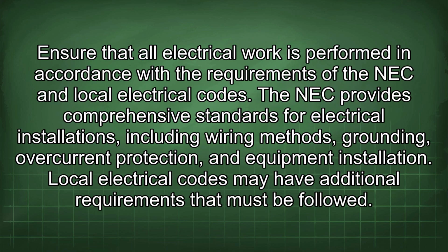Ensure that all electrical work is performed in accordance with the requirements of the NEC and local electrical codes. The NEC provides comprehensive standards for electrical installations, including wiring methods, grounding, overcurrent protection, and equipment installation. Local electrical codes may have additional requirements that must be followed.